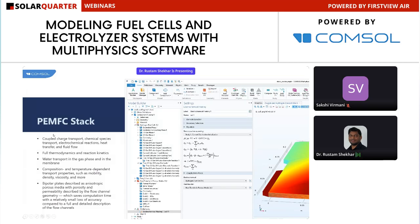So we have the coupled charge transport, chemical species transport, electrochemical reaction, heat transfer, and fluid flow. In this stack level model, we will take the full thermodynamic support for the reaction kinetics, water transport in gas and liquid medium, composition, and temperature, which will give you the new properties like transport properties, mobility, density, viscosity, and more.